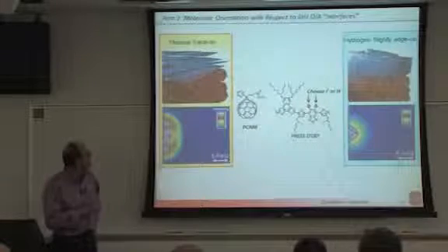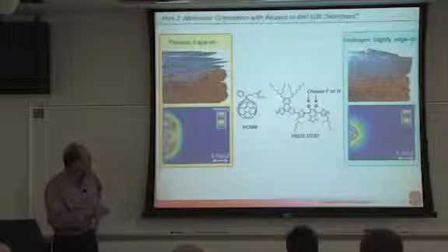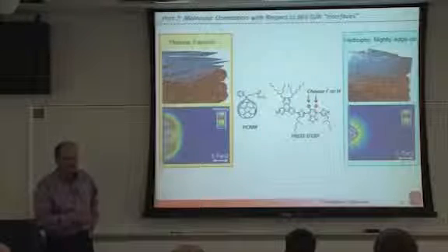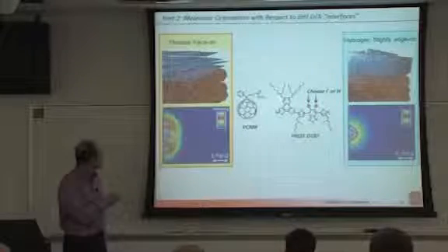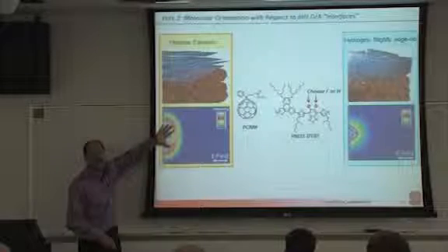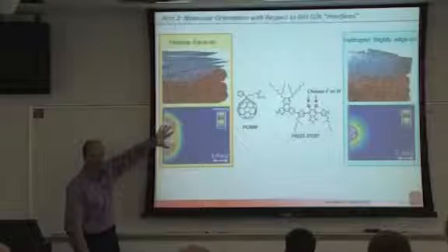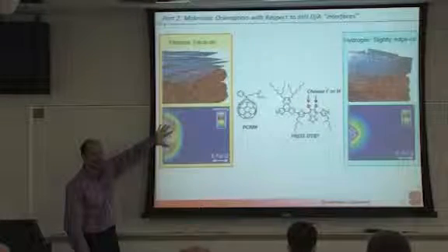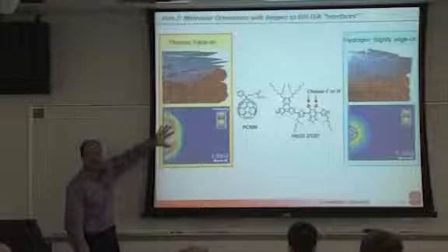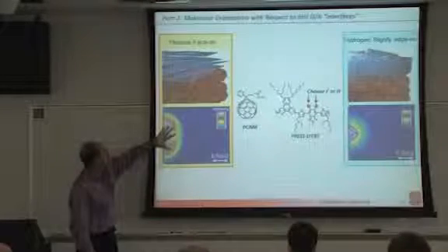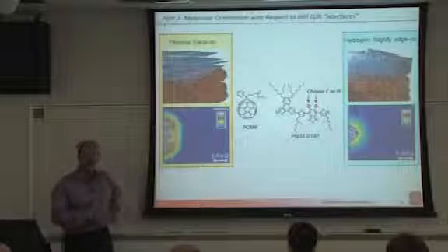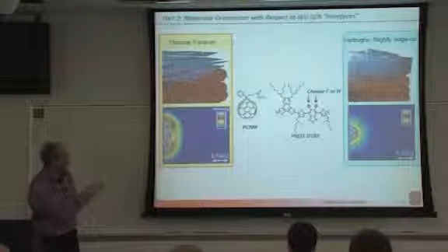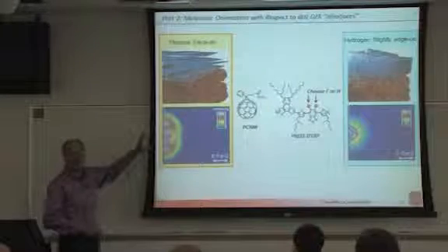acceptor system. So in this particular material, PNDT, DDTBT, again, with or without fluorination, depending on the processing, we get very different scattering. You see some of this asymmetry. You've seen that earlier, but I haven't explained it yet. And this asymmetry in the scattering has to do with the local orientation relative to a reference. And I try to explain that to some degree, but just as a highlight up front, this asymmetry we interpret as a face-on orientation relative to the PCBM domain.